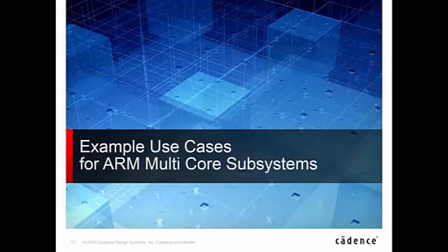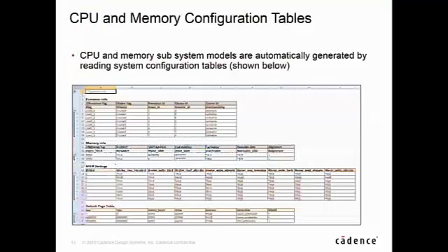So this next section, there'll be some repetition, but it's looking at the same kind of concept of going after coherency verification and how that is accomplished in the system. One of the things that we talked about was identifying what the CPU subsystem is going to look like. So in this case, you identify all the cores, what clusters are associated with the cores, what the cacheability of the core is, and any ID information.